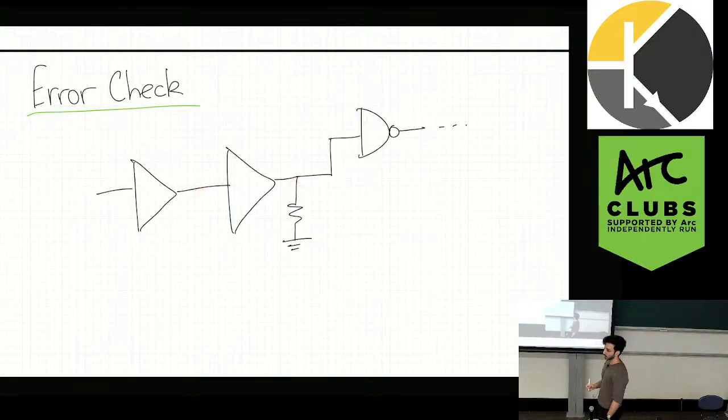But again, you only have so many pins that you can actually probe on a PCB, right? Your design manager might say, okay, I'm allocating you 3 pins on the PCB. That means you have to get creative with how you test errors in the system. Because if something goes wrong, and I haven't put in a built-in probe system on the PCB, I can't easily just probe it, especially if it's packaged with shielding.